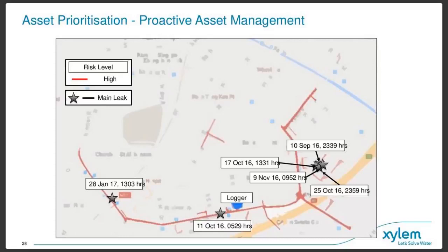So a few examples here are an overlay of identifying area of risk, and then the validation that leaks and bursts within the area, which are these little stars shown here, were related to customer activity within the network. And you can see that the impact of these pressure transients can travel over quite a large distance, but it can be very helpful to understand where the areas of the risk are, and also areas that aren't seeing as much stress.